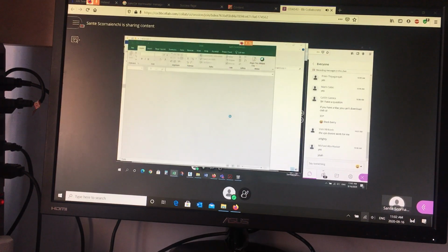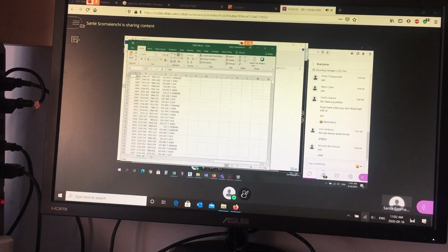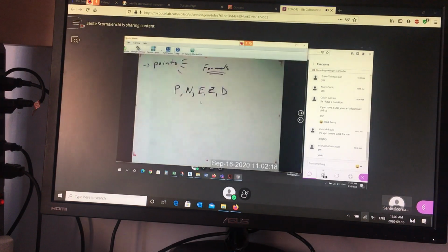So you have to know the point file format, right? Notice there's no title. It doesn't tell you that's the point number. It doesn't know anything that's easting. So you have to know the file format. If you don't know the file format, then you can run into problems. Okay? There are many file formats. The one we're going to use is always going to be this one here.